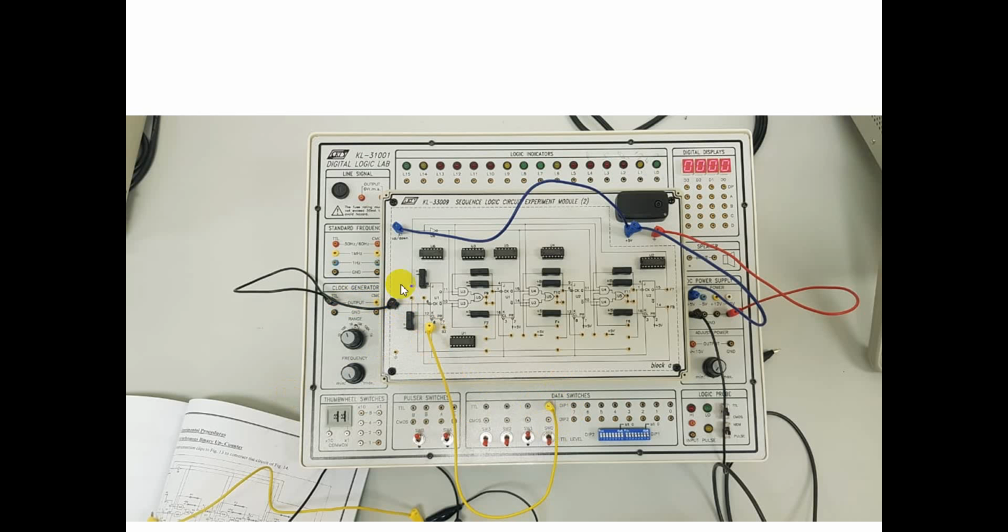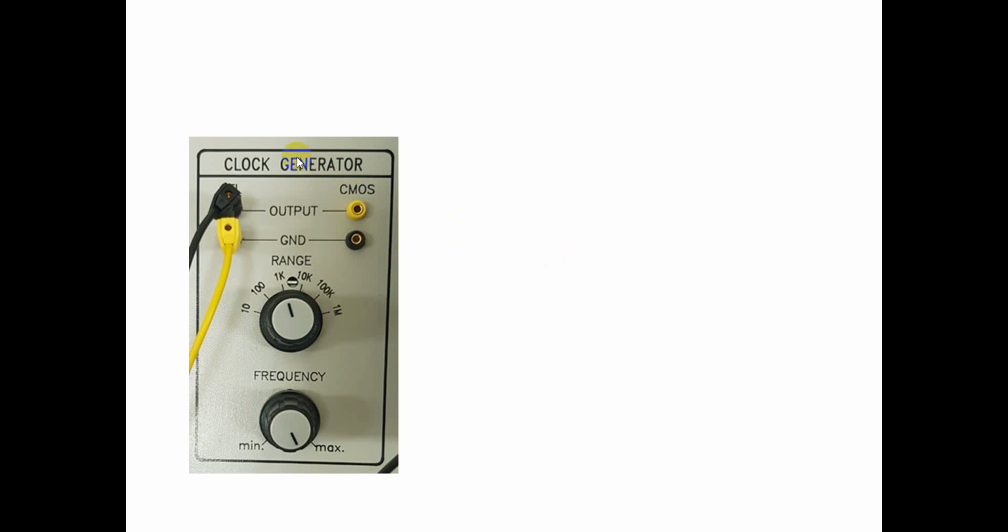And in B1 here, I'm going to give a clock signal. So first, before giving the clock signal, I need to adjust the clock here. I just connected it to show you the diagram. So please go through it, and we can discuss in the lab session if you have any doubt. Now, according to the manual, we need to give a clock signal which is 1 kilohertz here. So how will we do it?